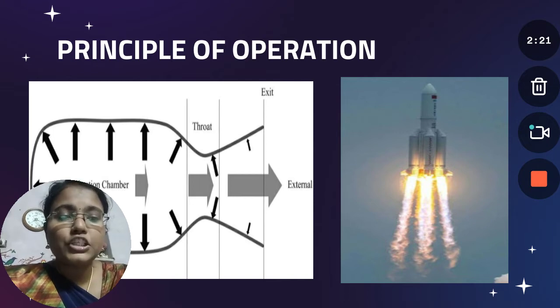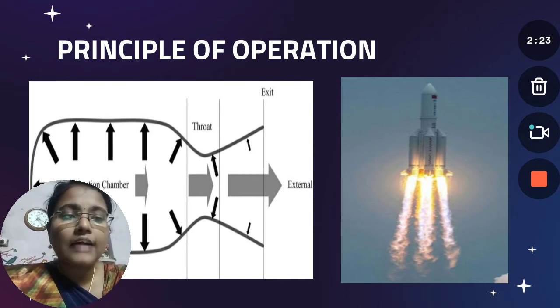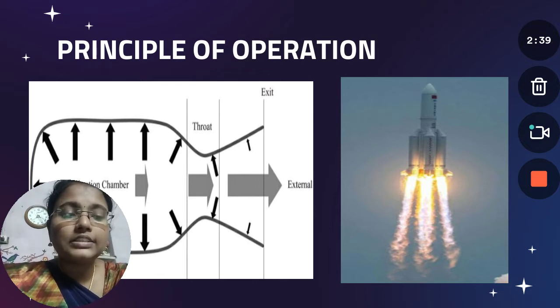In addition, the pressures act on the exhaust in the opposite direction and accelerate it to a very high speed. This disequilibrium of pressures can be maintained for as long as propellant is added to the combustion chamber. It turns out that the speed of the exhaust of the rocket determines how much momentum increase is created for a given amount of propellant.